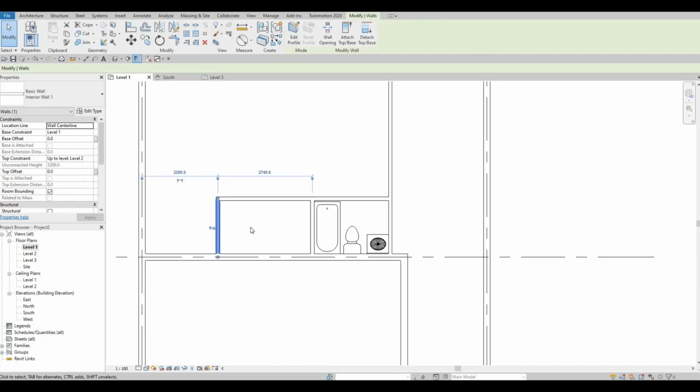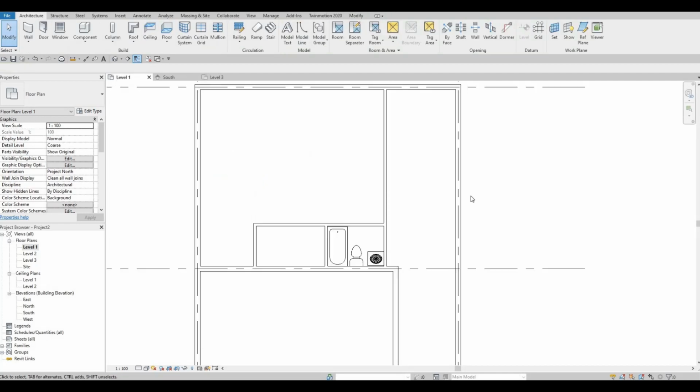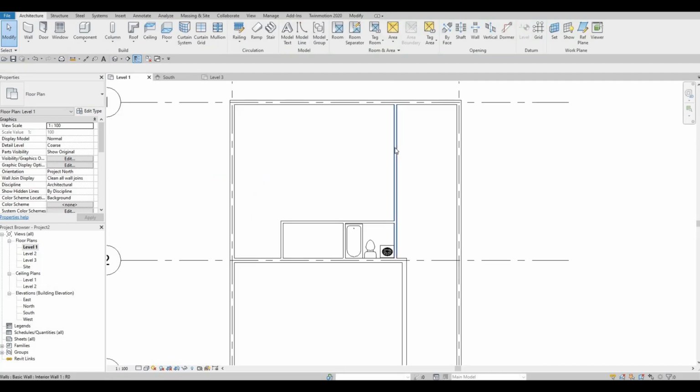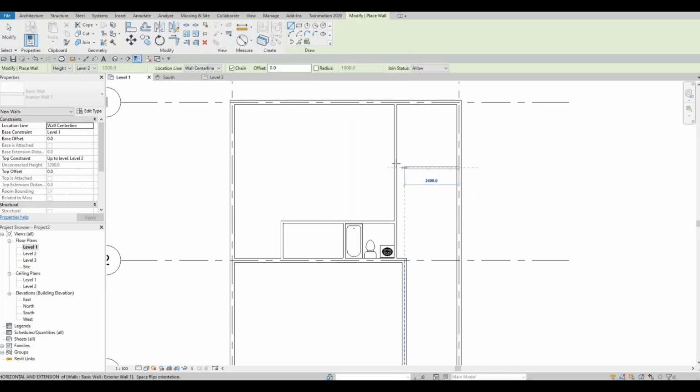We're going to add the stairs right here, and there will be a storage underneath. So we're gonna edit this later on. Now that we have an interior wall right here, we're gonna add a bedroom at this spot. So we could just select this wall and reuse it by type in CS or create similar. So we're gonna add a wall right here.